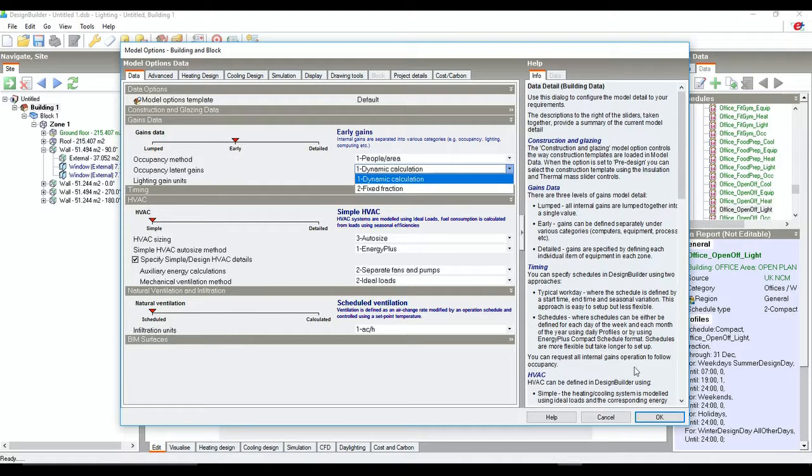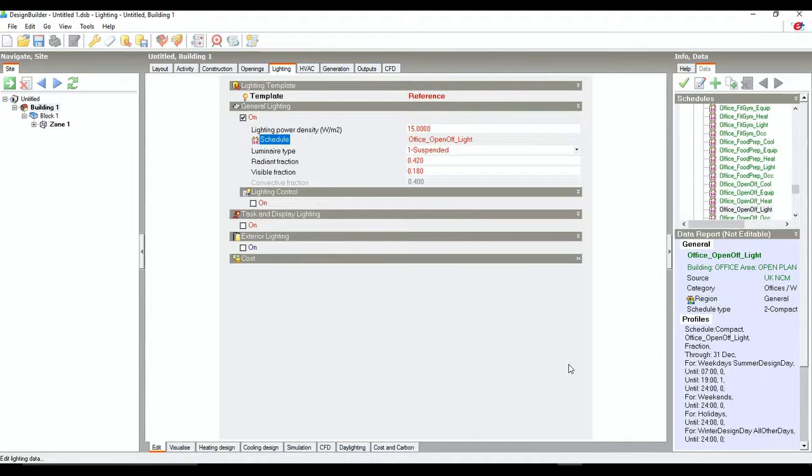So after you do that, if you just click OK, that will update the total area, and as you can see that now it's 15 watt per meter square, and you can change that also from the standard guides of CIBSE or ASHRAE.